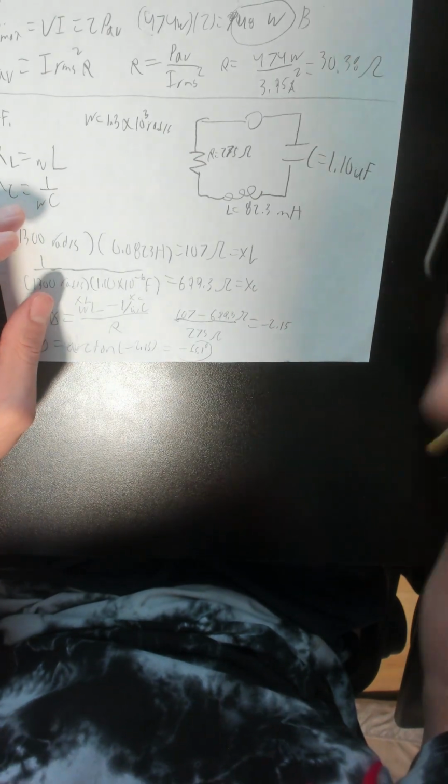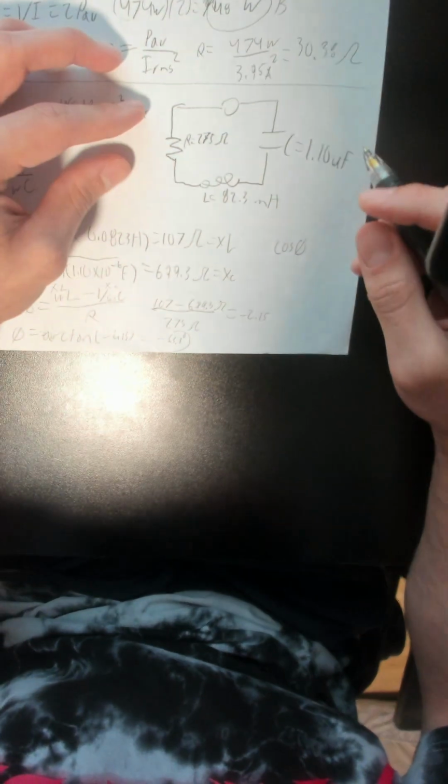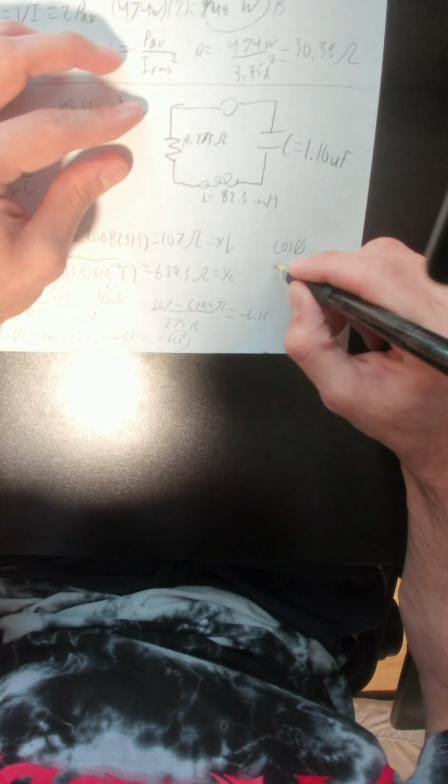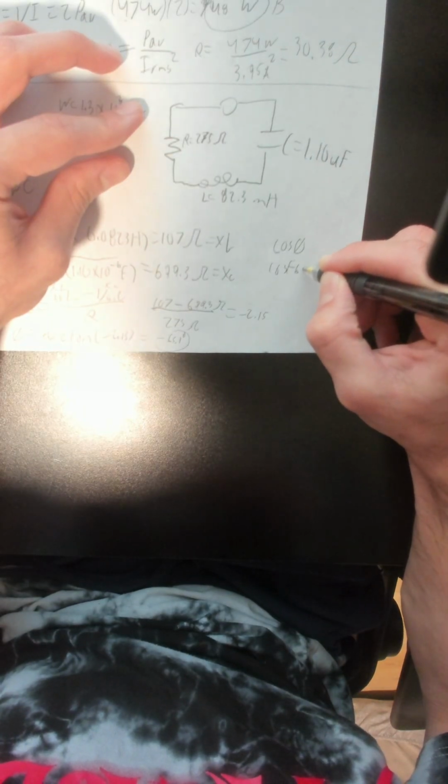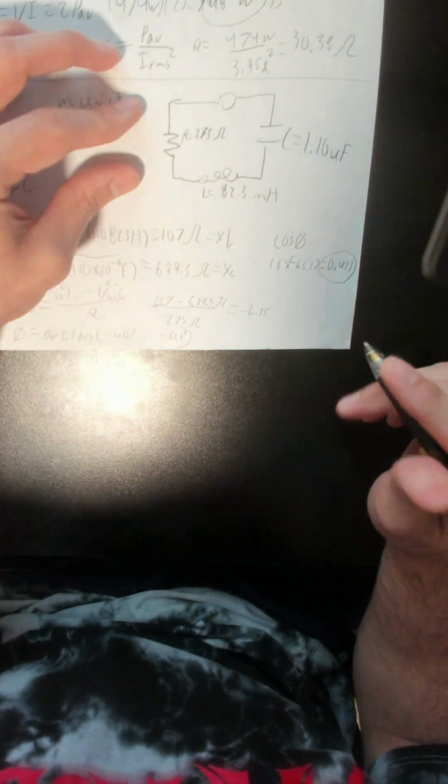and now we just have to find the power factor. The power factor is going to be the cos of the angle. So cos of the phase angle, I mean, which is simply cos of negative 65.1, which is equal to 0.421 for part F. All right, 0.421 for the power factor, F. All right, let's move on to the next question, which is going to be part G. And it's going to use the same information we had from the last three. So for part G to I,